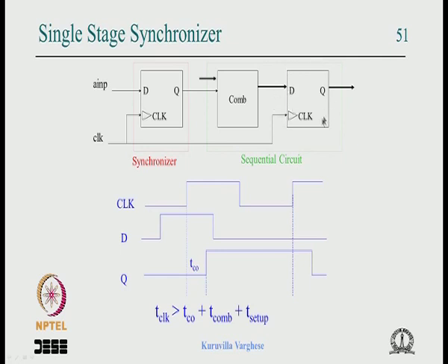In a sequential circuit there could be 20 flip flops, and an asynchronous input reaching the 20 flip flops can put all the 20 into metastability, okay. But now we are catching that analog input in a single place, okay. Earlier it might propagate through different combinational delays.